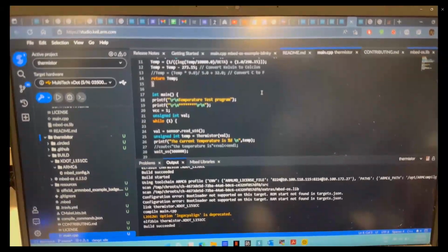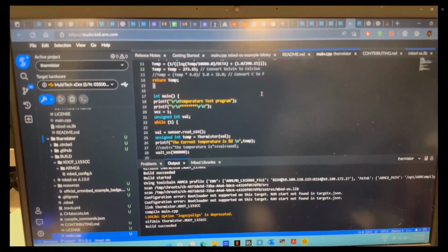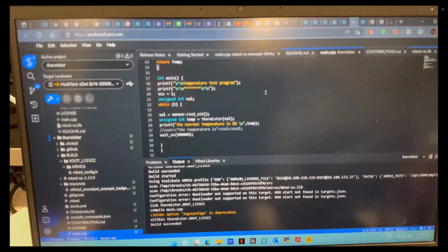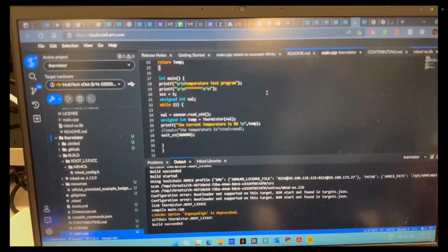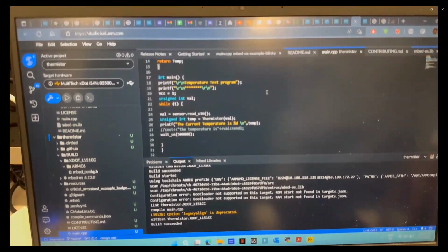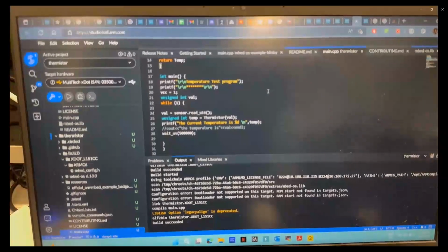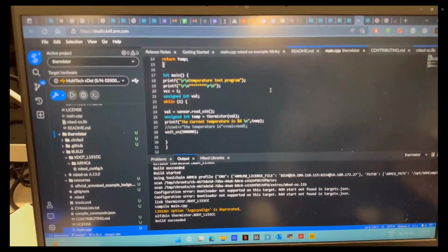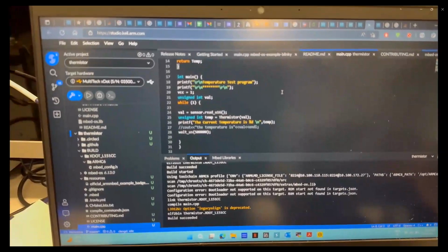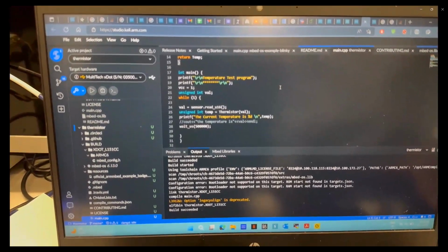The sensor reads the 16-bit unsigned value, and the ADC will convert it into the temperature value in Celsius. We do some calculations here to convert from Kelvin to Celsius, and this is how it mainly looks. The code and the readings are given every 5 seconds.